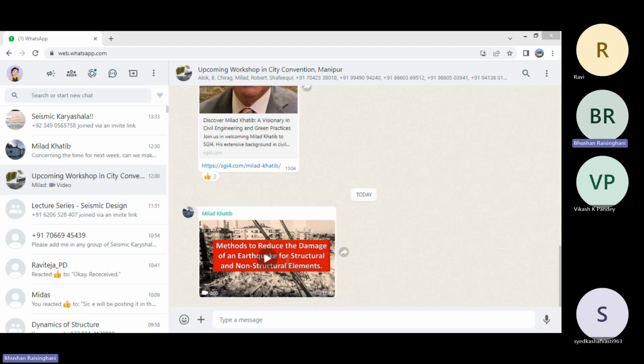The diagonal of a coupling beam shall be anchored in the adjacent walls with an anchorage length of 1.5 times the development length in tension. See figure 16. So what would be the anchorage length? 1.5 times the development length, that is Ld. So that much reinforcement has to be extended into the shear walls, 1.5 times the development length Ld.